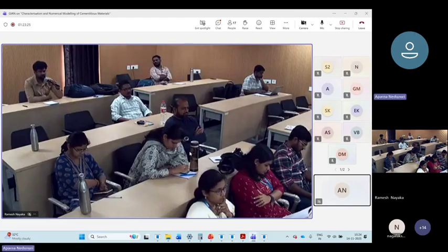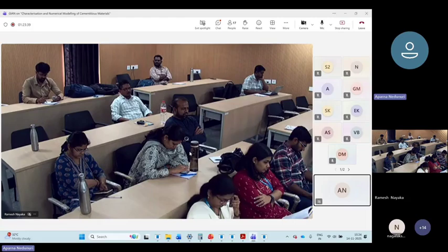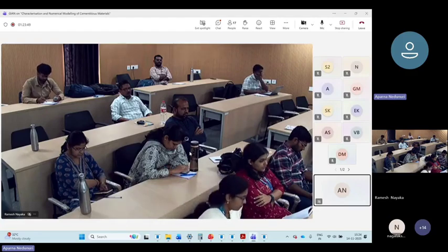No, no, no. Never. You could not match only one two theta position. You need to match all the two theta positions. So that's a good point which I didn't bring out. When you're picking up the cards that I have shown in the Qualx software also, it's not only one or two peak positions that we have to see. You have to see almost all the peak positions, and you have to ensure that most of these peak positions are matching the card that you are selecting.